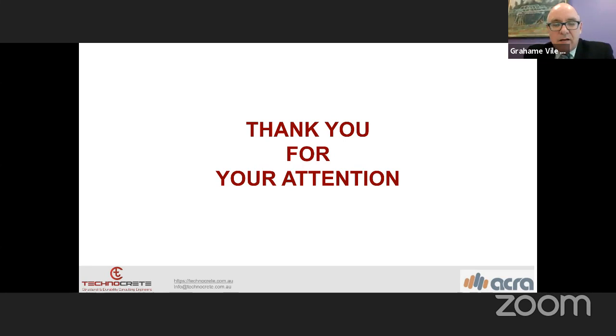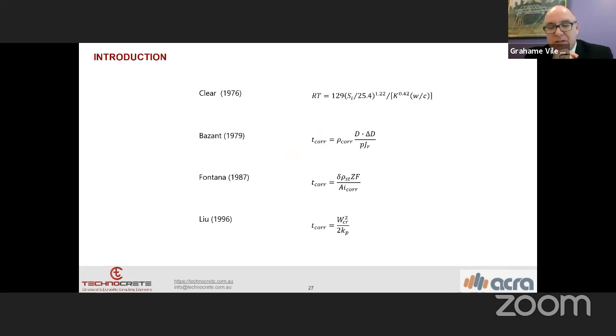In the analytical side, this is one about the modelling of deflection. Comments been made that ACI has recommendations on how to model the influence of crack depth with structural response, particularly around changing the EI of the member. You can simulate the loss of capacity. Yes. That's pretty much the basis of your, yes, in some circumstances, yes. Okay.